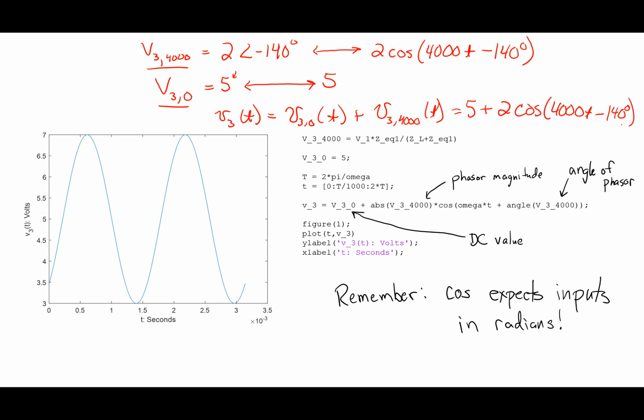Important thing to remember about this is, again, this is the steady state voltage. If I looked at this, there would be some transient as well, and the transient would be over within usually a much, much smaller time than a single period. There is some e to the negative t over tau sort of thing going on here. We're not looking at it. There always is a transient response, but we're only doing steady state when we do these AC circuit things with impedance. Questions about this?